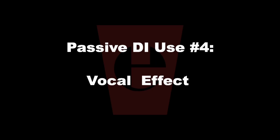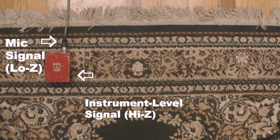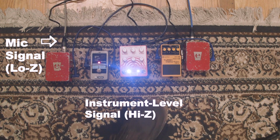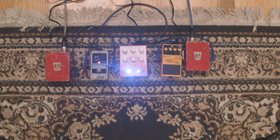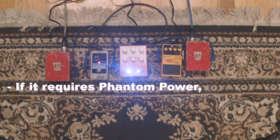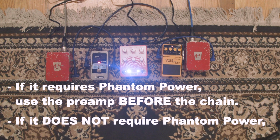You can also use a series of DI boxes as a means of getting an effects loop in place for vocals. The first DI converts the mic level signal to instrument level and high impedance, which the pedals expect to see. The signal goes through the pedal chain, then back into the second DI to convert it back to low impedance balanced mic level. Because transformers block DC and thus can't transmit phantom power, you'll need to use the output of the mic preamp if you're going to use a condenser mic or an active ribbon mic. Otherwise, you can go straight into the DI.